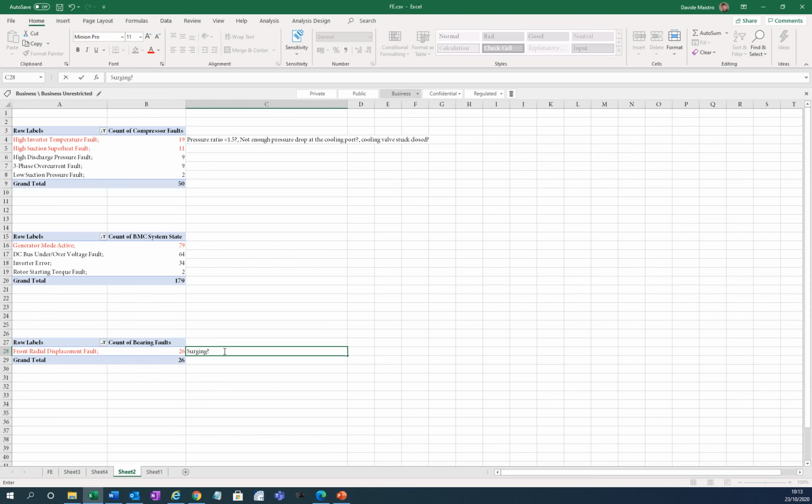the other question is when is the compressor surging? So during ramping up, during part load, during shutdown. For each of these situations, there are quite a few registers on the compressor that can be adjusted in order to fine-tune the compressor to that particular application. Okay.